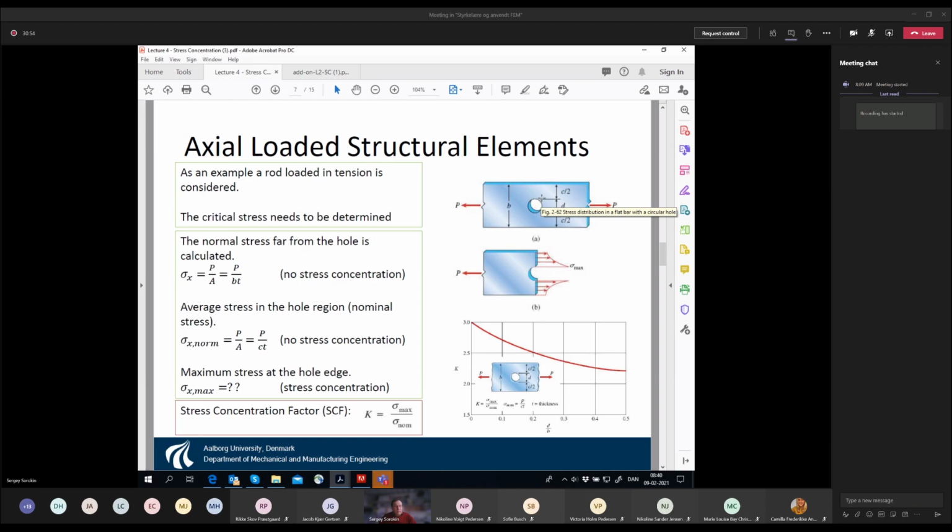And then this increase in the curvature. So if you go down to the extreme, so if you say that you maintain this width, but this distance comes to 0, then this maximum stress turns to infinity. And this is the mathematical result, which has been obtained, as I say, something like maybe 100 years ago, 150 years ago. So this is something which is very well known.